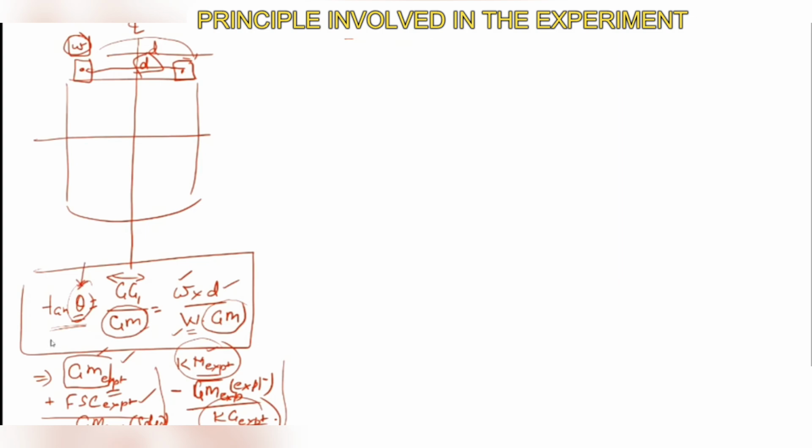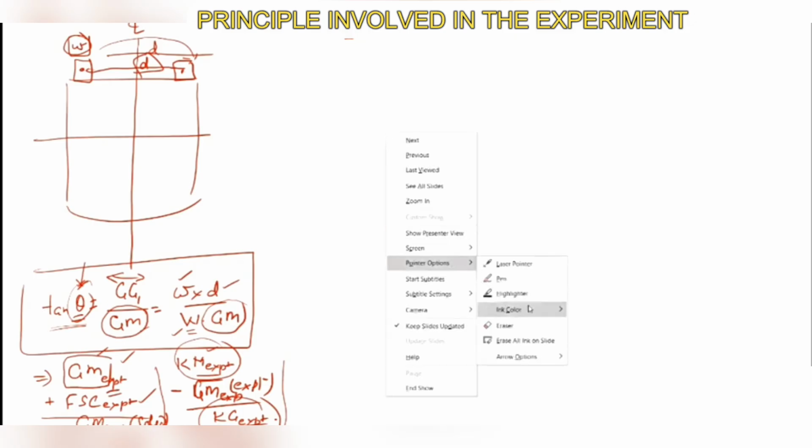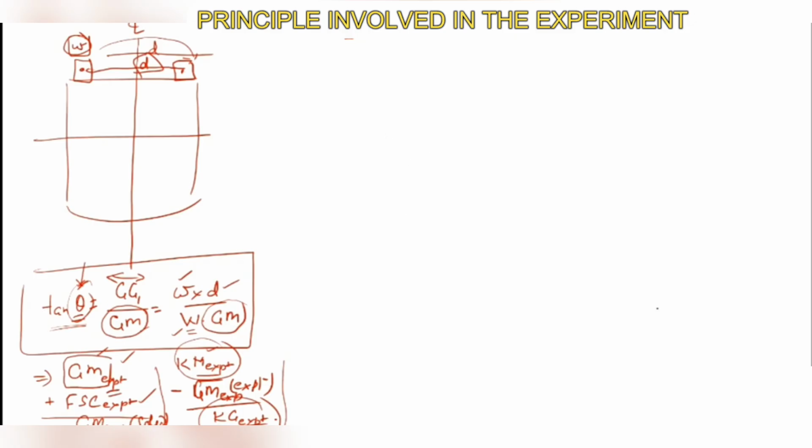So how is theta measured, or how is the list measured? Now, to measure the list more accurately, we make use of a pendulum. A pendulum is suspended on the bulkhead on the center line. Okay, here it is suspended. And we also take a graduated scale which is fitted to the bulkhead. So this is the graduated scale which is fitted to the bulkhead, and the pendulum is suspended here. This is the upright condition with the weight being here. Correct, guys? Is that clear? This time the list is 0.